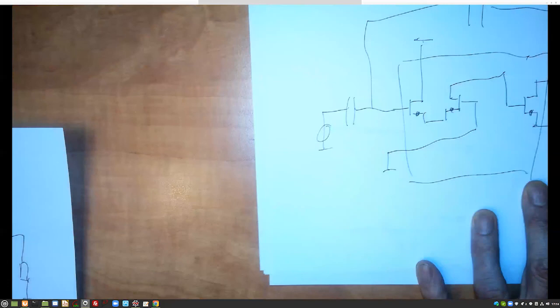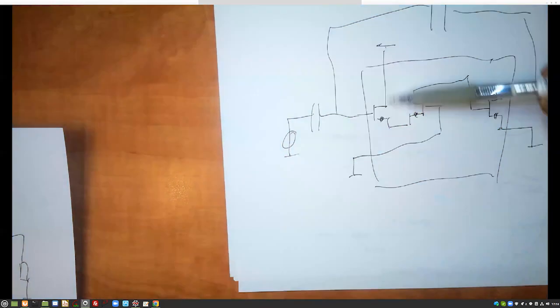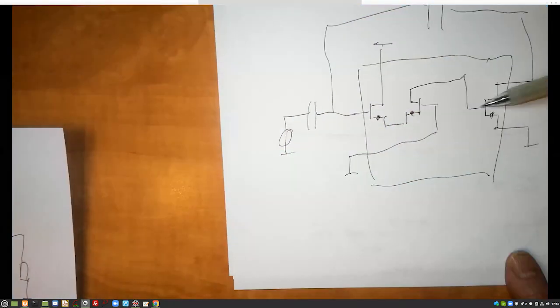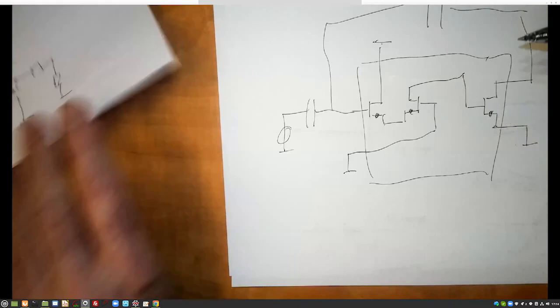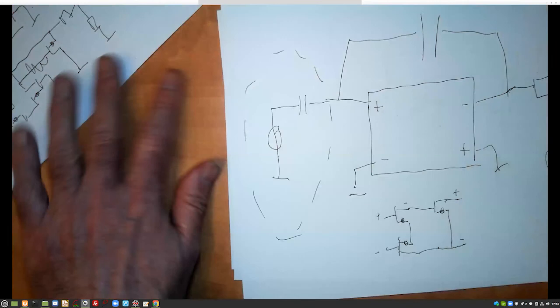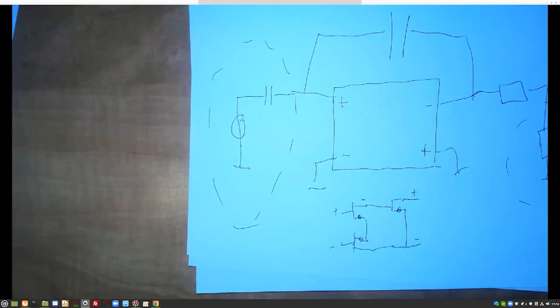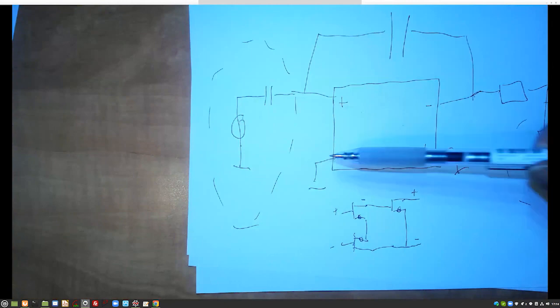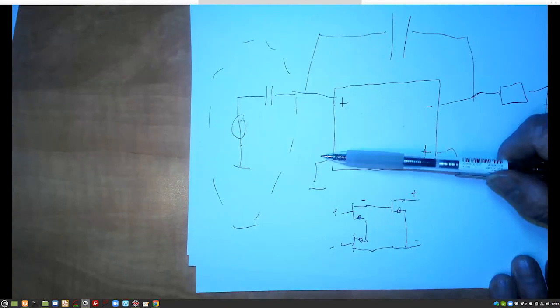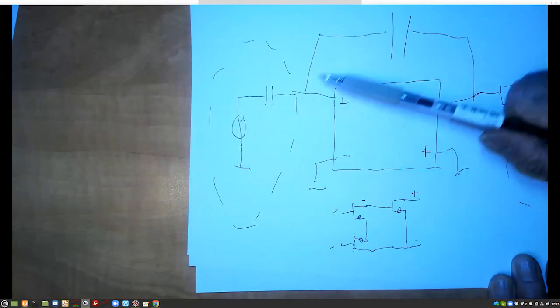It's very formal. The only thing you do is you connect the output of one stage to the input of the next stage, and you realize yourself what kind of degrees of freedom you have to place the whole thing in it. And why should I add this inverting voltage source that was just a test circuit for my differential pair? So I saw here people placing the -1 gain controlled voltage source. We are building an amplifier. So this was the amplifier.